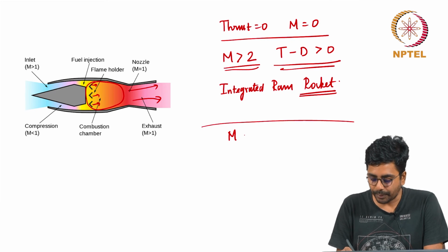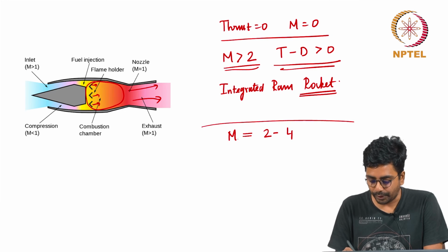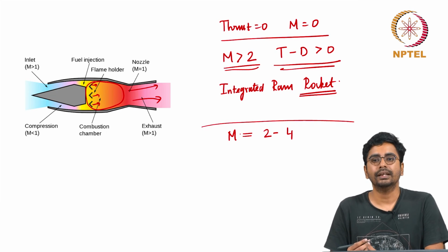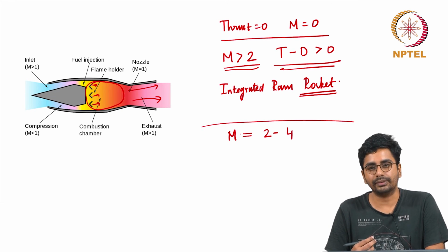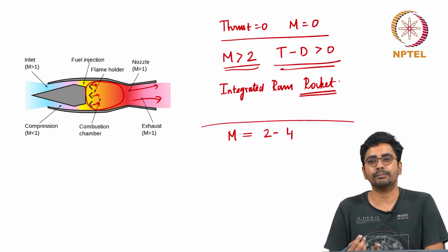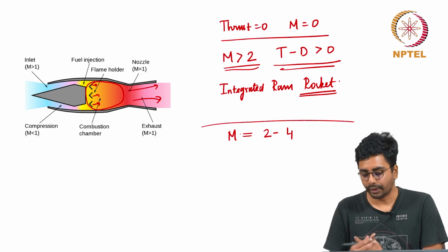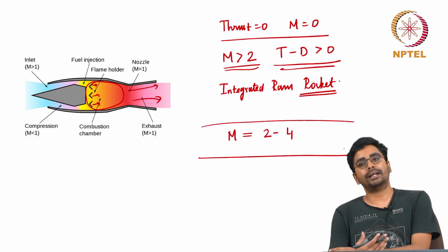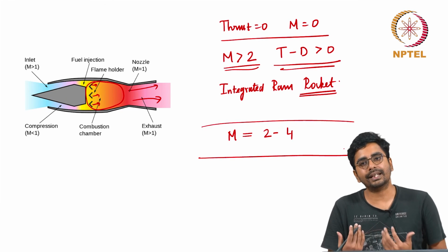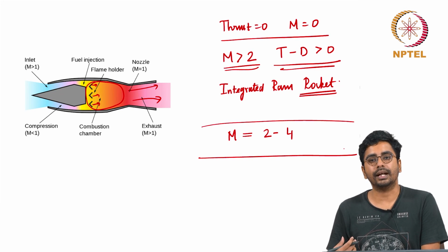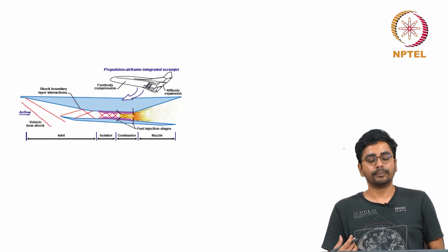the optimal operating point is in the range of Mach number 2 to 4. What happens when you go to Mach numbers beyond 5 is that the result of the deceleration process is air at such high temperatures and pressures that there is very little room for addition of enthalpy by adding fuel, because temperatures are so high, whatever fuel is added, the fuel will simply decompose without adding enthalpy to the flow. So when the flight Mach numbers go beyond 5, it does not make sense to decelerate the incoming air to subsonic speeds, because the scope for adding enthalpy is very low.